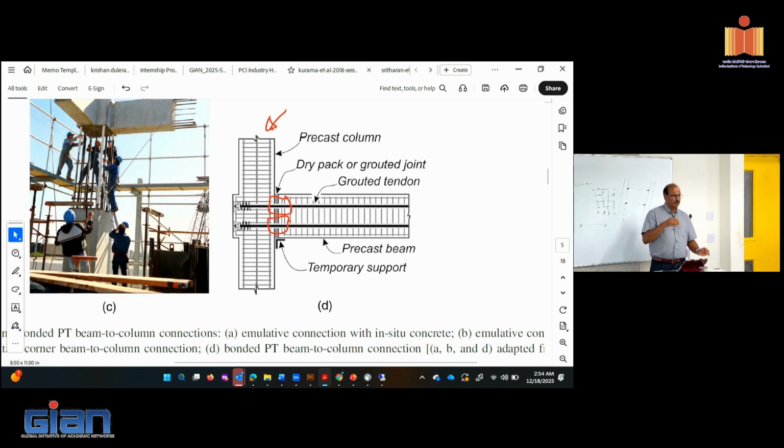So the Japanese still went in that direction, and then they had the 95 Kobe earthquake. Between the two earthquakes, the 94 earthquake in California tested some of the parking structures, which basically took the emulation concept and put it to the test, whereas the Japanese let their buildings go through this type of structure to see how well it performed. In the Northridge earthquake, almost every parking structure within a certain radius of the epicenter was damaged significantly.